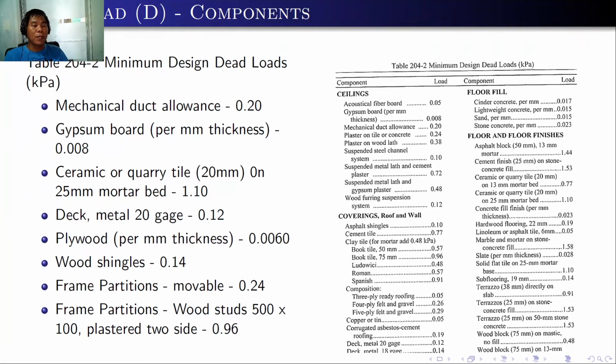If you are using for floor finish ceramic or quarry tile that is 20 millimeter on 25 millimeter mortar bed, you will be using 1.1 kilopascal.